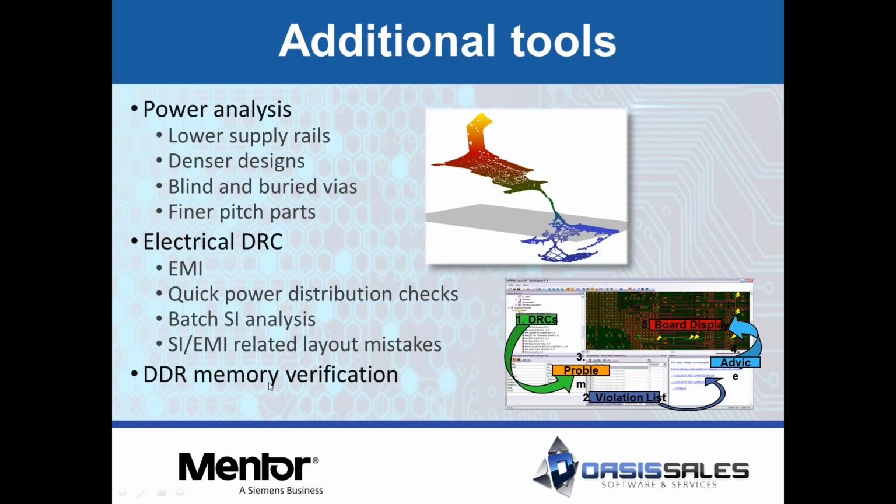Many of you out there probably know it, but there's probably a lot of you that are trying to do DDR on board and just going off specifications. And it can work in some cases, but a lot of times, again, you don't know what you don't know. And if you're not doing some type of verification on those DDR channels, you may not get it right the first time. And any spinning of a board costs money and could easily pay for a tool that you'll be able to use over and over again as time goes on.